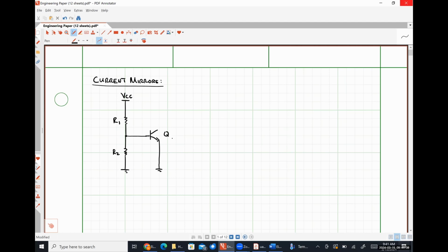This is going to be transistor Q1, so I'm going to use Q for all of my BJTs, M for all of my MOSFETs. And we don't really particularly care what's connected to the collector terminal of this transistor Q1, which is why I'm just putting a ... here. It might be more transistors, it could be a resistor, it could be a direct path to ground, it could be a direct path to VCC. We don't know, nor do we actually care at this particular moment in time, right?